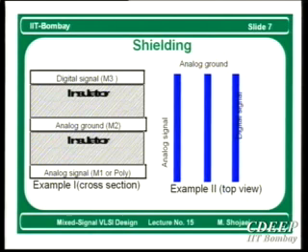For example, if I want to use one single bias, which is not even recommended nowadays, and then I want to route an analog current for a long distance, then that node should be able to drive a large capacitance. These two cannot happen at the same time.